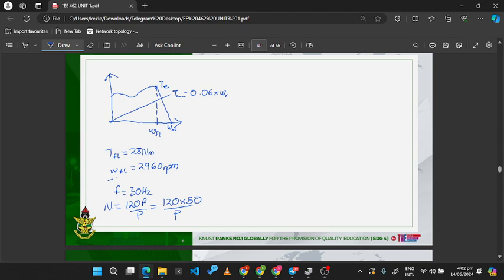So we need to calculate the synchronous speed, n_s, that is closest to 2960, and of course it has to be above that. The least number of poles a motor can have is 2 poles. So if we assume the number of poles is two, let's check it. With that, we get a synchronous speed of 3000 rpm. So now we also have the no load speed omega nl as 3000 rpm.